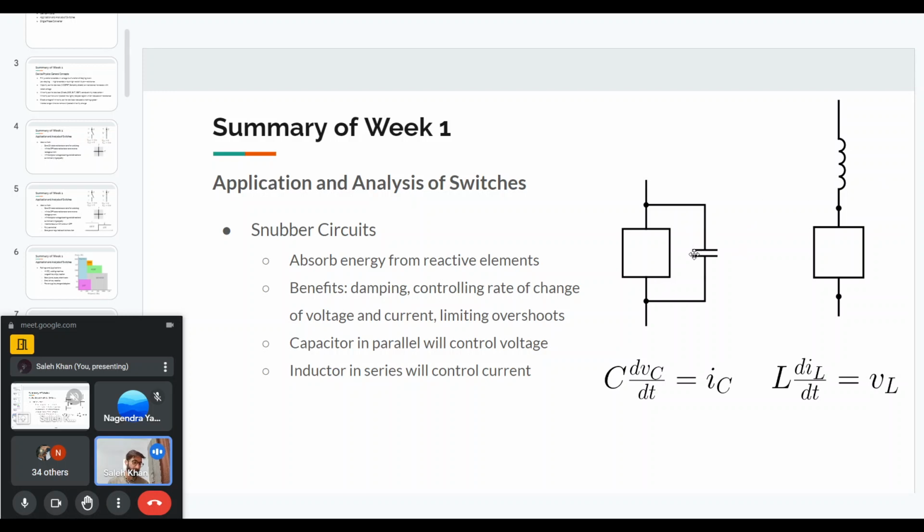so that those resistors will basically dissipate or absorb this energy, because what we want is also, because the snubber circuit can also reduce the switching loss. They can take some energy, and that energy will then be dissipated in the additional resistors that we will include. So you're right. The capacitors and inductors by themselves will not absorb energy. They will only transfer energy from one place to another. But the dissipation will happen in resistive elements that we will include in the snubber circuits.